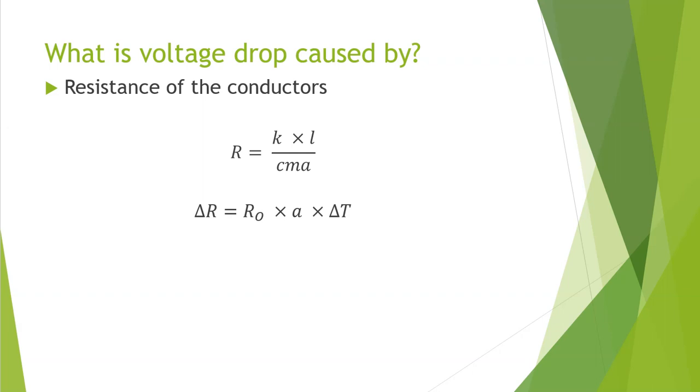If it is a larger AWG gauge, then the resistance of that circuit for a given length and a given type of material will be lower than one where the AWG gauge is a smaller gauge. Then in addition, the temperature of the installation comes into play. Where the conductors are operating at a higher temperature, they will naturally have a higher resistance.